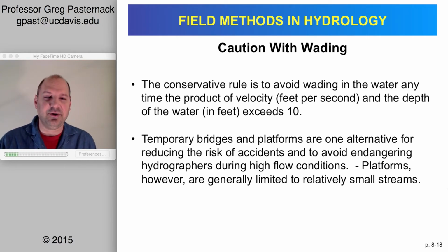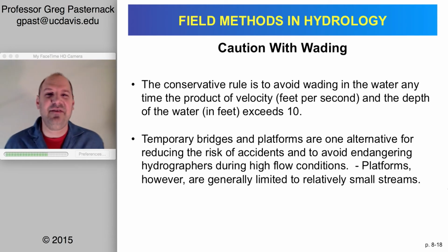So that's another factor. If you want to get velocity measurements in flows approaching bankfull or of course in flood conditions, you're probably not going to be wading out into the river. Instead, you might put a platform across. If it's a small creek, you might put a ladder, like a fireman's ladder across it, or maybe 2 side by side, and be able to go. Make sure you've tested this and know what you're doing in safe conditions before you go out during a flood, of course.